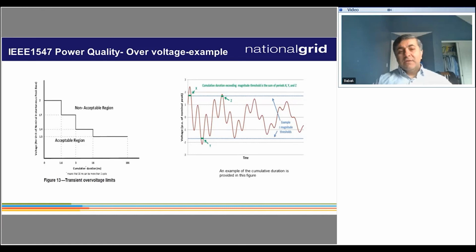We looked at what's out there in terms of available documents that we can use to specify the even sub-cycle requirements for overvoltage. So we looked at the ITIC curve, also known as the CBEMA curve. We looked at the Hawaii interconnection guideline, which has transient overvoltage requirements, and then we compared those with typical surge arrester damage curves. And we came up with this figure, the curve that you see on the left side.